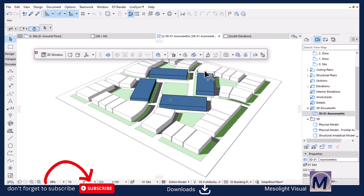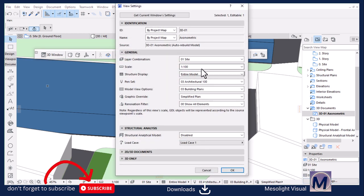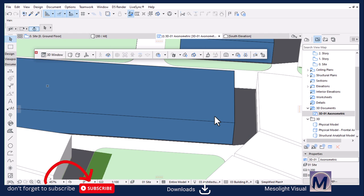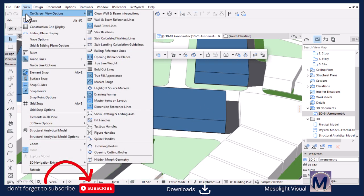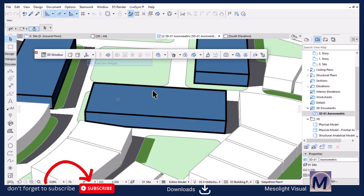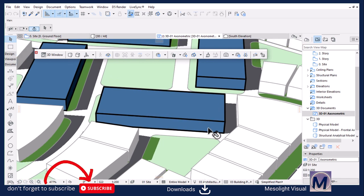It's a big plot, or it's a big project. So what we need to do is change the scale in order for us to see the change of the thickness of the outline. Let's set it to 200. Then from here, go to the view and on-screen view options and activate the true line weight. You see, now you have the outline.